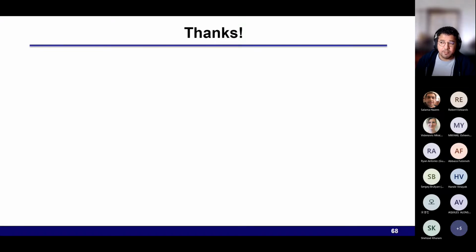For instance, at the time, the vSub was connected to everything, right? With Magic, you can extract the design, but the substrate is all connected to all the transistors, so that's not good, right? Those are the types of things we found out.